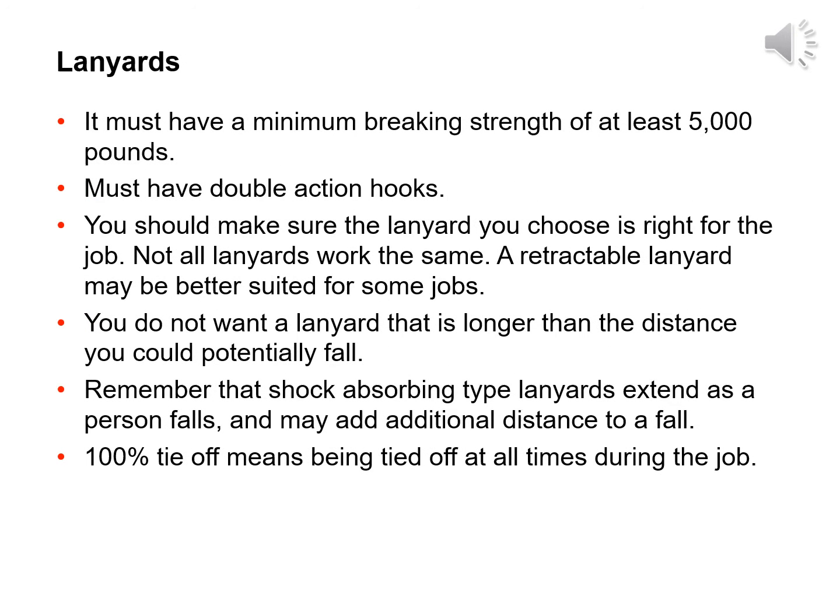Lanyards must have a minimum breaking strength of at least 5,000 pounds. They must have double action hooks. You should make sure the lanyard you choose is right for the job. Not all lanyards work the same. A retractable lanyard may be better suited for some jobs. You do not want a lanyard that is longer than the distance you could potentially fall. Remember that shock-absorbing type lanyards extend as a person falls, and may add additional distance to a fall.